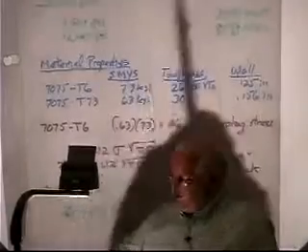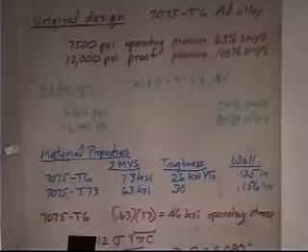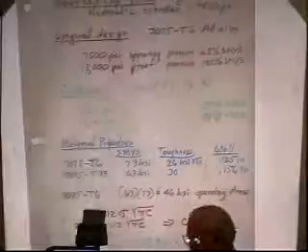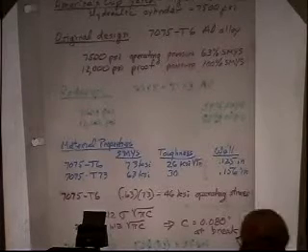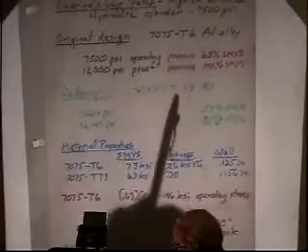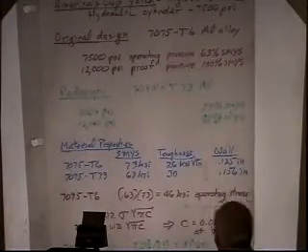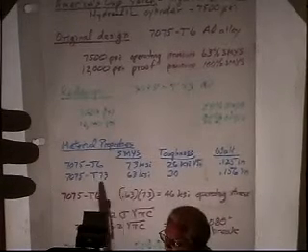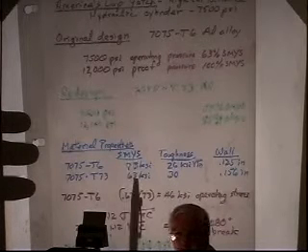In any case, the redesign that I suggested was to go to 7075 T73. Now remember that little aluminum washer I said from the helicopter I bought? This was because I had worked on that. And I knew that the 7075 T6 was susceptible to stress corrosion cracking. That looks like a stress corrosion crack to me, but we won't go into that. So I said, well, go change from the T6 heat treatment to the T73, but the problem is, and you can't read this, the yield strength of the T73 is down from 73 KSI to 63.